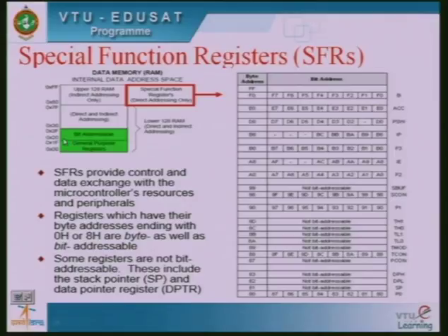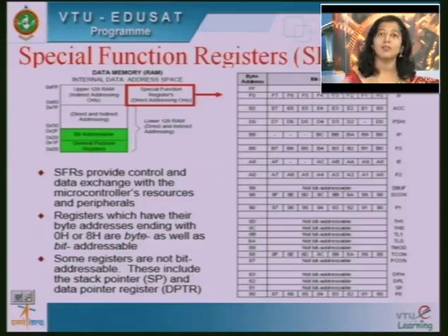To set values in the peripherals also, we use different control registers. Serial control sets the correct control operation for the serial interface. Then there is interrupt enable: if I want to enable external interrupts, I make this high. So, I have different control registers where I can set each bit separately to do different control operations, especially when the microcontroller is communicating with its peripherals. You should be able to control how that operation happens.